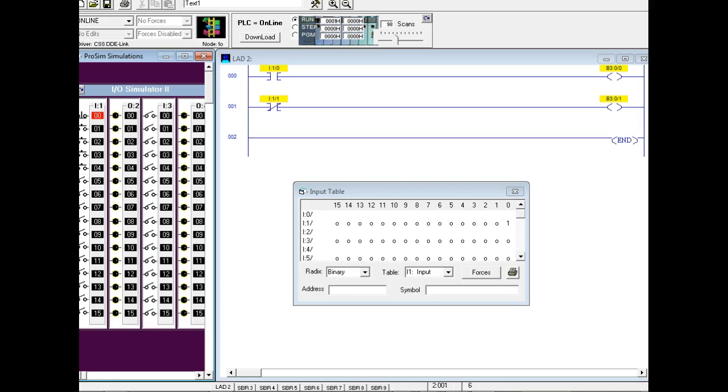Don't get this confused right here. You understand? Okay, so it's drawn as a closed contact. A closed contact means, okay, if what it's looking for is true, then it's closed. Examine closed says, well, if what I'm looking for is open, it's false. That's the problem. I was trying to relate it directly to the contact, to the symbol, instead of what's true and what's false. Okay, y'all understand? So here I'm getting a true back. Right, you understand. Well, it's a normally closed contact.